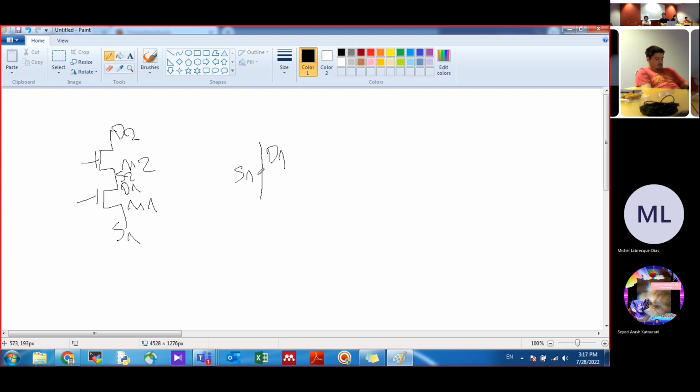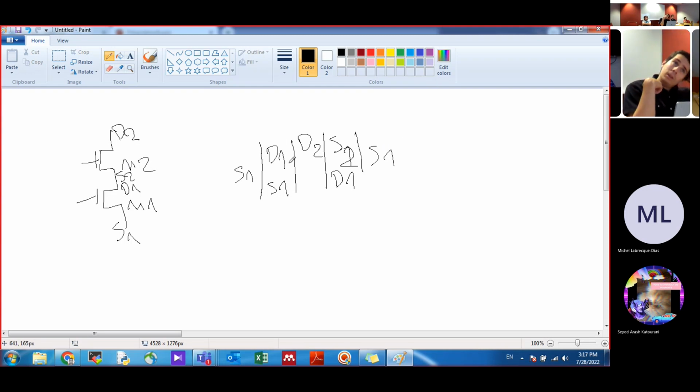And because in MOS technology there is no difference between source and drain, so you use S2 over here. Then the gate for this one, and then a gate, and then it will be S2. Then the S2 is already D1. Then come back to the S1, and then come back to the top.